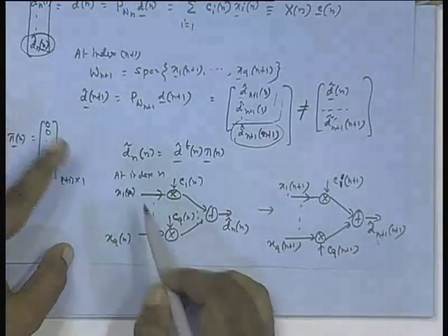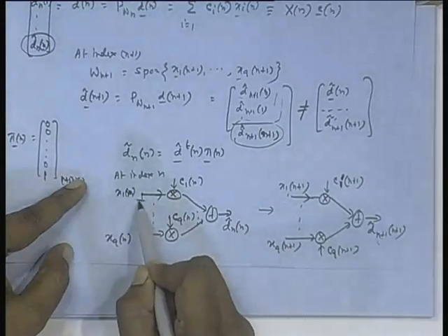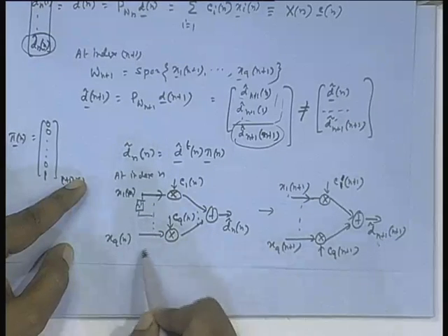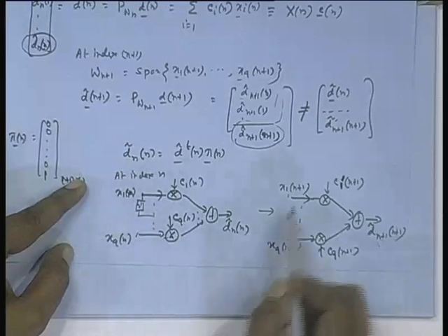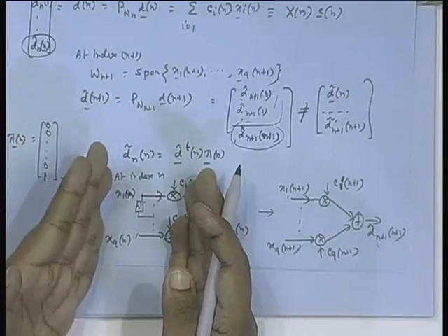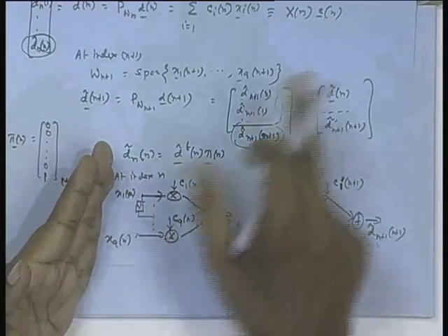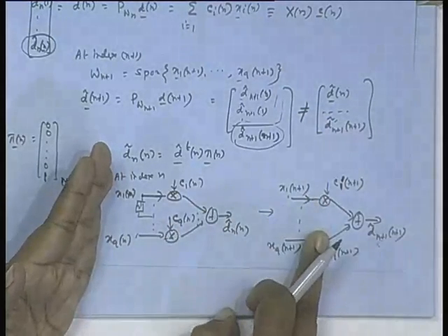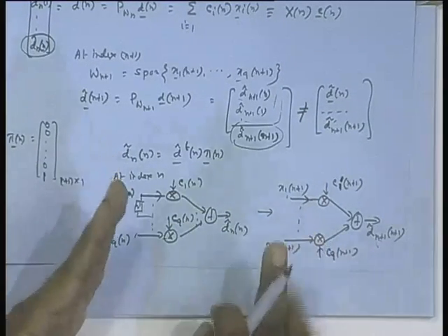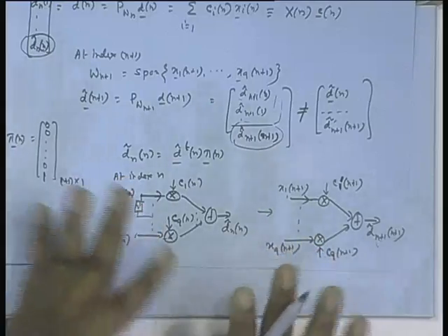Here it is more general. If it is a filter, x1 n, there would be a delay here, then x2 n, there will be a delay here, x3 n dot dot dot, and finally a delay in this. Same here, then it becomes a FIR filter. Coefficients will be adapted by that recursive least square algorithm to the new set. Okay. So, you understood the philosophy involved here.